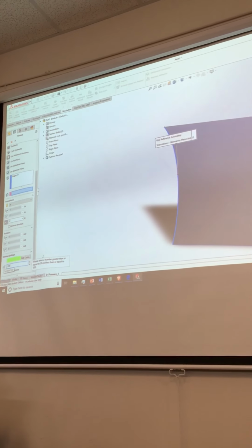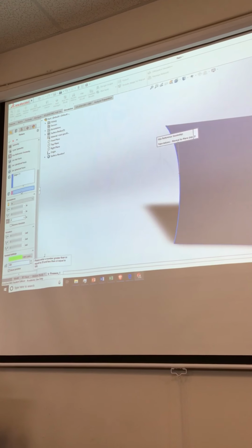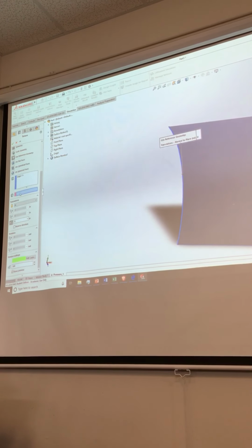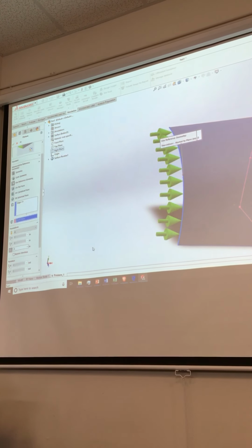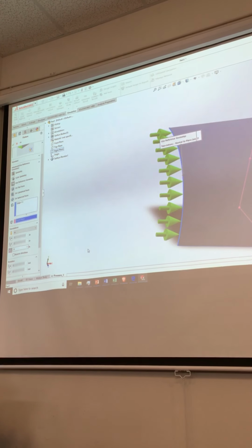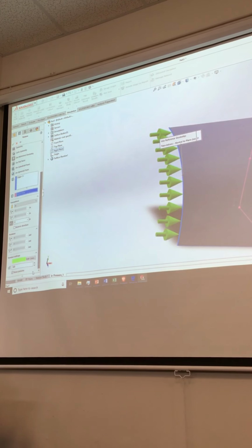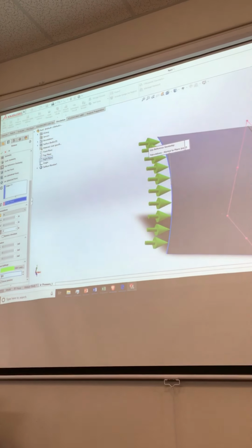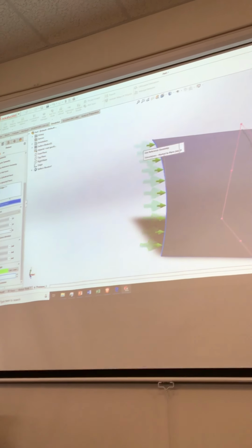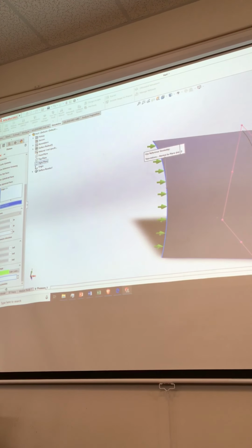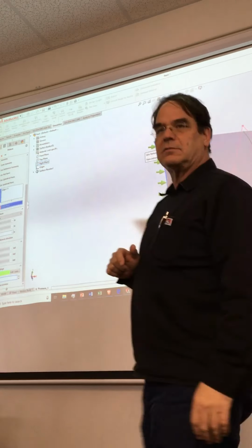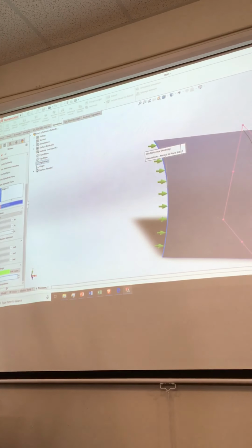Selected the plane. Yeah, you haven't selected anything, so the arrow's not. Oh, okay. I selected the right plane. I thought I did. Okay, there we are. Okay, big arrows. I got big arrows. So you think those are too big? Yeah, I'll get back to 200. Okay, so we got big arrows, right? So that selects the out of plane boundary, right? So that's part of a symmetrical boundary condition, okay?